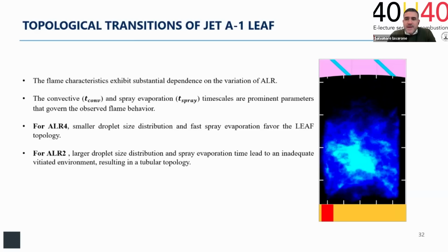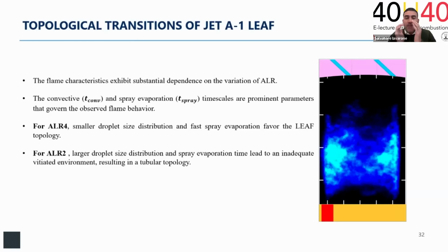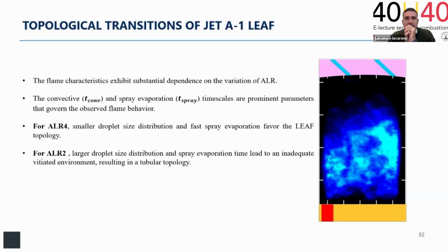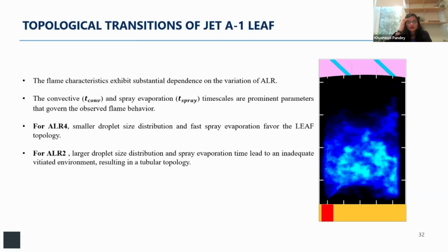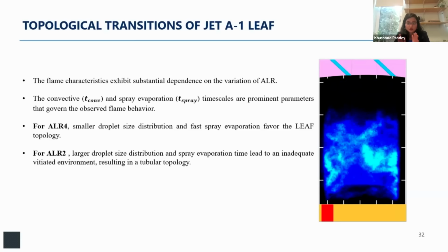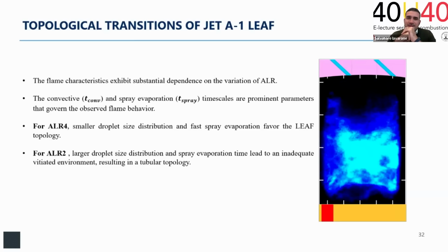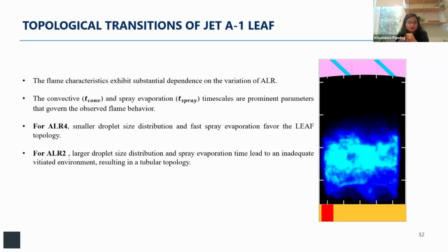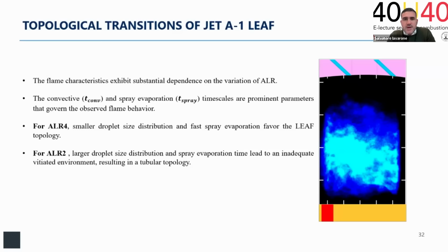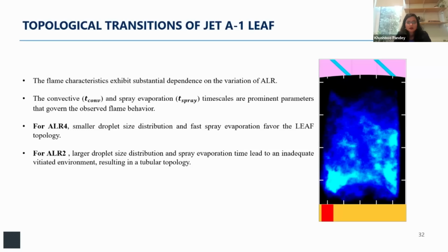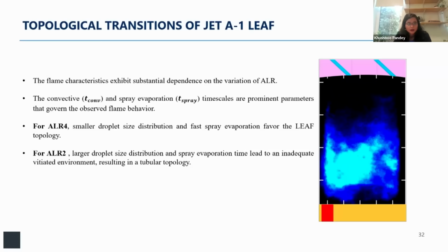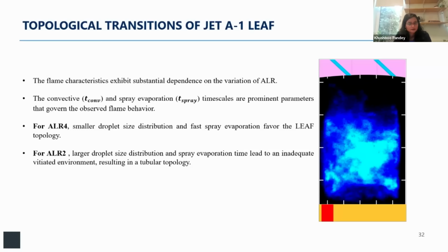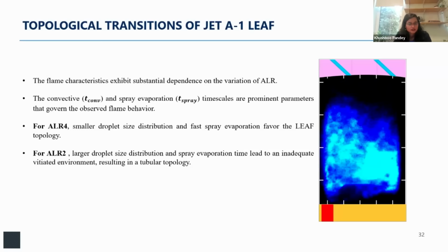And I was thinking, if you have now 6 optical quartz windows, how did you manage with the heat loss? Yeah, so these are actually 12 windows. Each side has 2 windows, one inside, one outside, and in between the two, there is an air cooling flow. So technically, all the windows are cooled all the time. When the LES was done, this cooling was taken into account to account for the heat losses, using conjugate heat transfer.